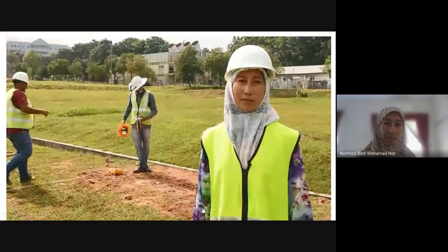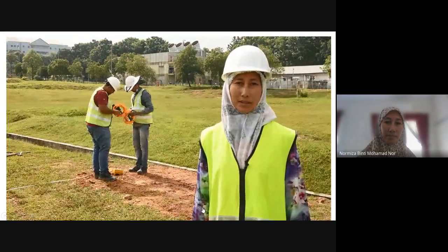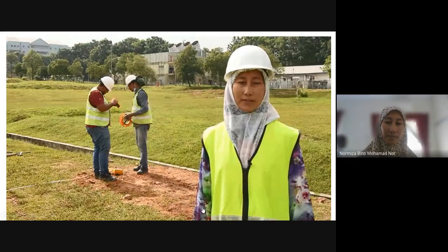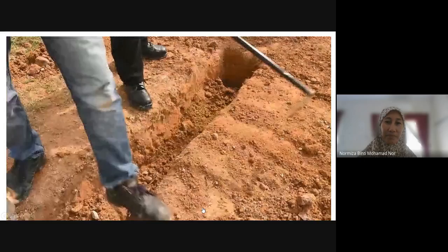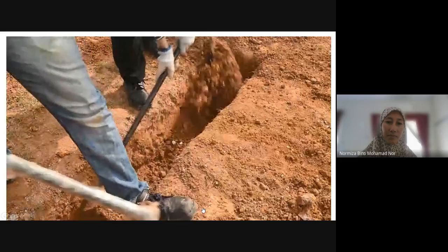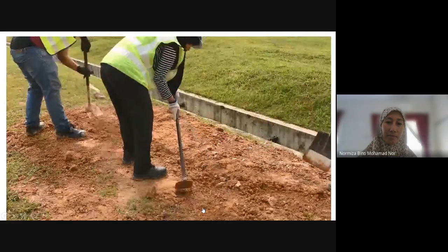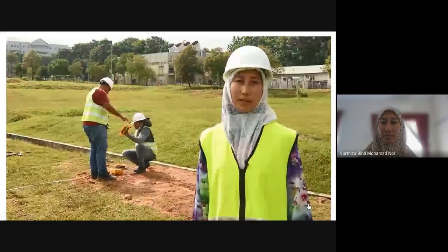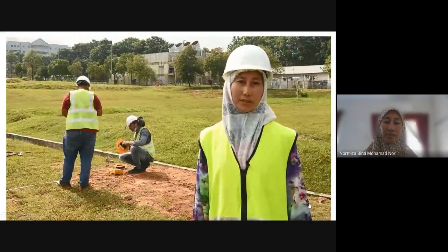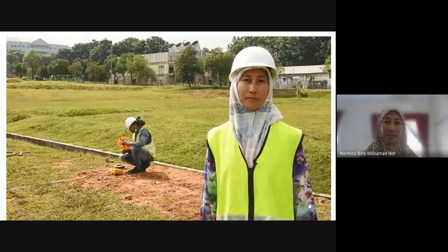electric field from the pipe ground electrode is 4 times higher than the conventional electrode. Other than that, we have also seen that because the pipe electrode is facing downward, most of these currents and voltages are very much concentrated at the downward pipe electrode. Therefore, it will reduce the potential rise above the surface of the ground electrode.